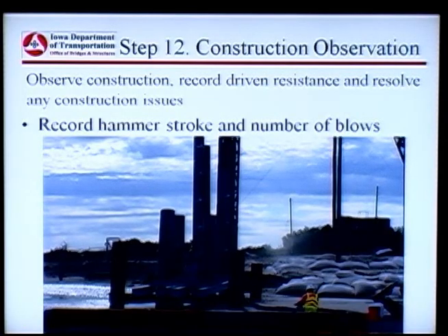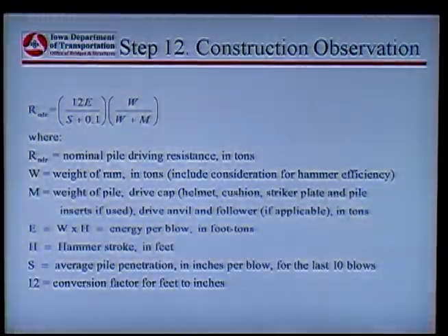Again, you observe the construction. You record the driving resistance in terms of the blow count, the number of blows per foot or number of blows per inch, and resolve any construction issues. And this information, the hammer stroke and the number of blows, will be used in this dynamic formula.